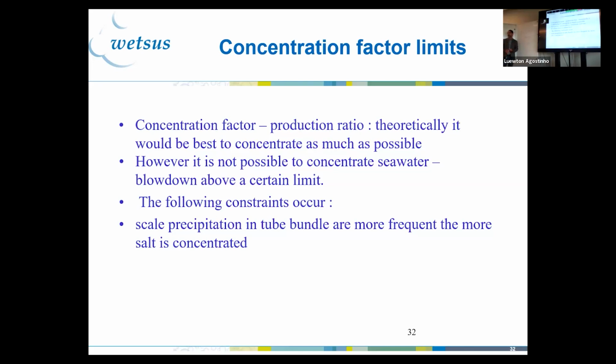You have to change your tanks. You have to change everything. So this is a problem. You cannot go very high in concentration, because then you have fouling. Scale precipitation in the tube bundles is more frequent the more the salt is concentrated.